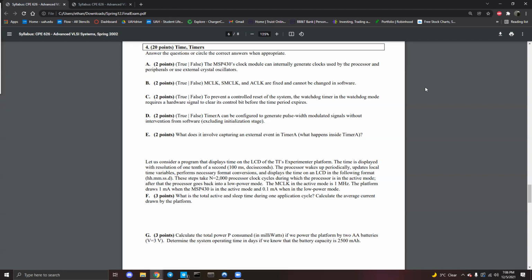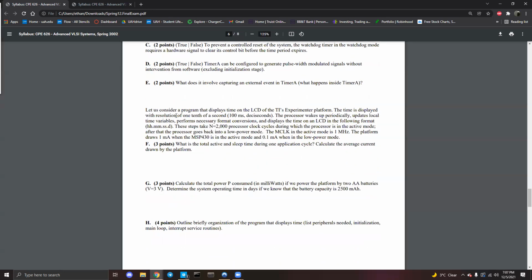What does that mean? In short, I attached an accelerometer to pin 3.4, which I happen to know is timer B's CCR3 multiplexed pin, in input mode, and I sent something in, which is then read and captured and held. You just shove something onto the pin. That's your external signal changing; the current content of the timer is latched and sent to a capture and control register. You're done. Easy peasy. You basically just send a signal onto the pin, right? But that's all he says for it.